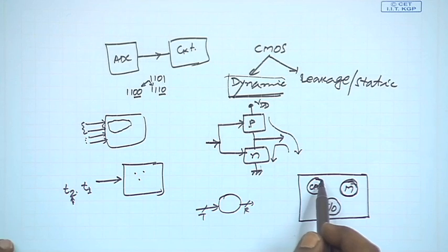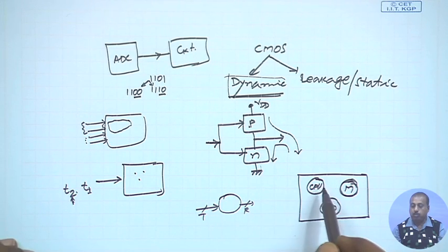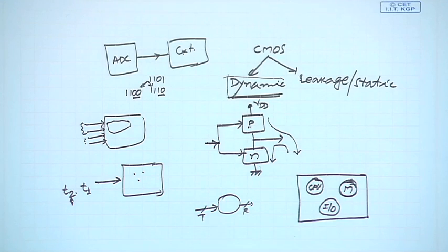But in this particular situation, we have got only a soft description of the CPU in terms of netlist from the vendor, and we are combining them into one, and on a silicon floor we are going to manufacture them. Now, even if my manufacturing process is 100% correct, there may be impurities in the silicon. No silicon is 100% pure. As a result, the CPU might not have been fabricated properly. So, I need to test the CPU even if my manufacturing process is 100% correct. That way this testing is required.